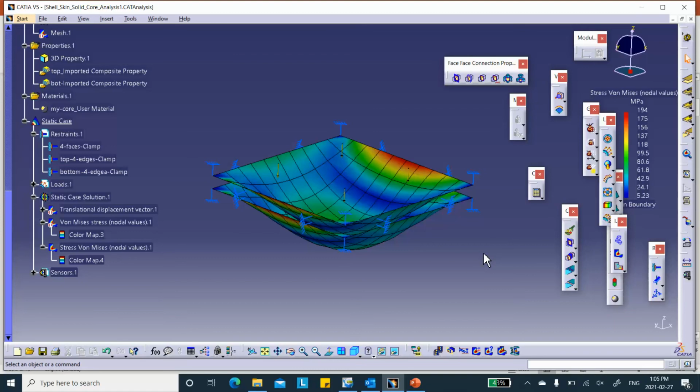And here, what happened when I meshed the top and the bottom and I swept that volume, the nodes came out to be exactly matching. But when you have an assembly, these nodes don't match, and you have to add some connections. Okay.